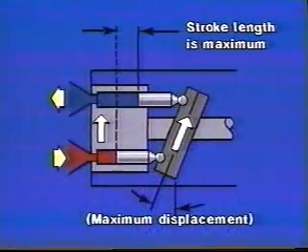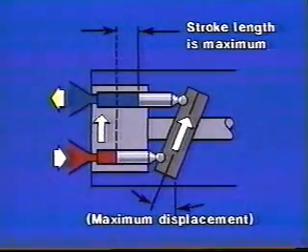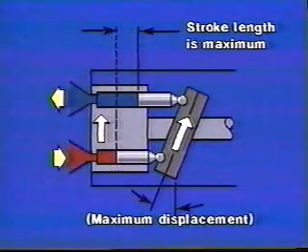Let's switch over now to a study of piston motors. Because of their construction, piston-type motors will usually allow us to operate at higher pressures and speeds than comparable vane or gear units. Here's a simple view of the inside of an inline piston motor. Oil directed into this port gives a force in this direction. Part of that resultant force produces a torque for rotation.